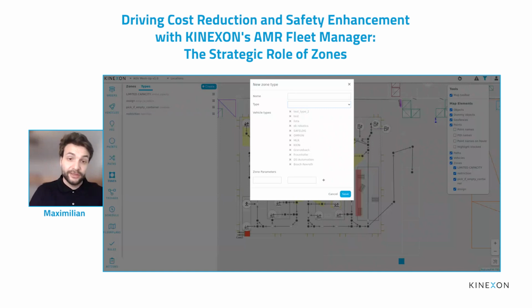But that's not always possible, because sometimes, or most of the time actually, you have a load carrier where you have a tolerance of 10 millimeters, like 1 centimeter. And if you drive under those, the cameras might detect it as an obstacle and the vehicle might stop, for example. And with this kind of zones, like the machine safety zones, you can tell the vehicle that even though your camera might detect something, please rely on your laser scanners instead and don't use the camera in that area. So you would turn on and turn off the camera in those areas, which is also a really big improvement for process stability if you're able to give that information based on the position of the vehicle.